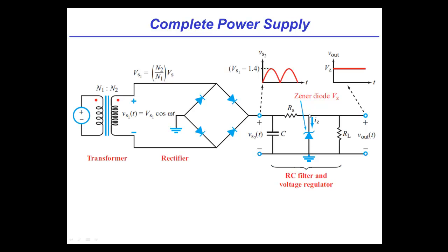Okay? And it'll ensure that the voltage across the Zener diode is held at a particular voltage, and that's specified by the manufacturer for the Zener diode. So you still need the rest of the circuit to get it up to that minimum point, but every time it goes a little bit higher in terms of those ripples, this thing just drains it down. Exactly. Keeping it totally flat. Yeah, so you need that filter, because if you didn't have that filter, anything below the Zener diode cutoff would propagate through. The Zener diode only cuts off above a particular voltage. Got it. So provided you've designed your filter properly, you can get rid of the ripple by ensuring that your Zener diode cutoff is below the ripple level. And that'll give you a really, really stable voltage.